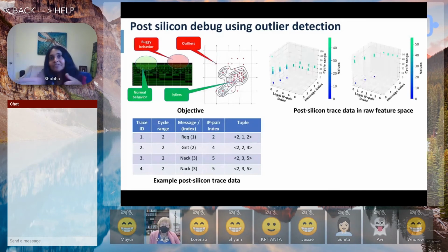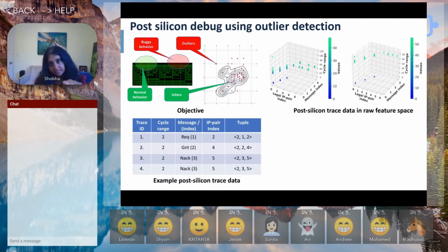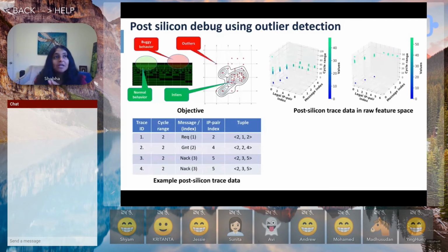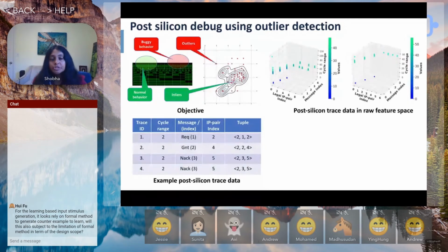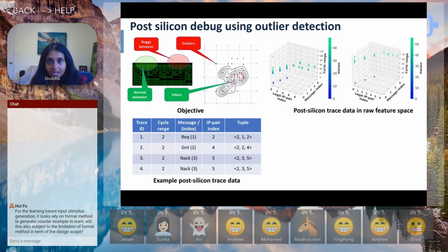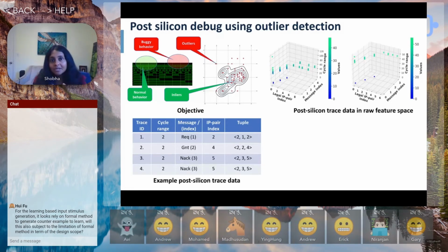In the previous cases, I showed you examples of how we did static analysis of the design and provided it to the ML algorithms so that they could come up with better assertions or better tests and so on. In one case, we used formal verification. In this case, none of that is possible because of the nature of the problem: we're running millions and millions of tests, and some of these tests failed, and at the end of that, this is a completely black box system where we don't have the luxury of the internal analysis that we were able to do in the pre-silicon case. In the post-silicon case, we only knew that there was a bug, and we had to work in this very black box environment that is inherent to post-silicon.